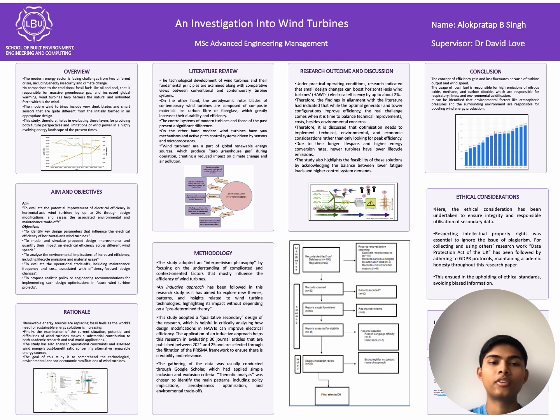Optimized blade aerodynamics, yaw alignment, and wake steering increased efficiency by 0.5% to 2.1% in aero servo electro simulations. The study has also found that the efficiency increases cut lifetime emissions by 0.7% to 1.5% per kilowatt hour and turbine count, reducing land usage and ecological disturbance.